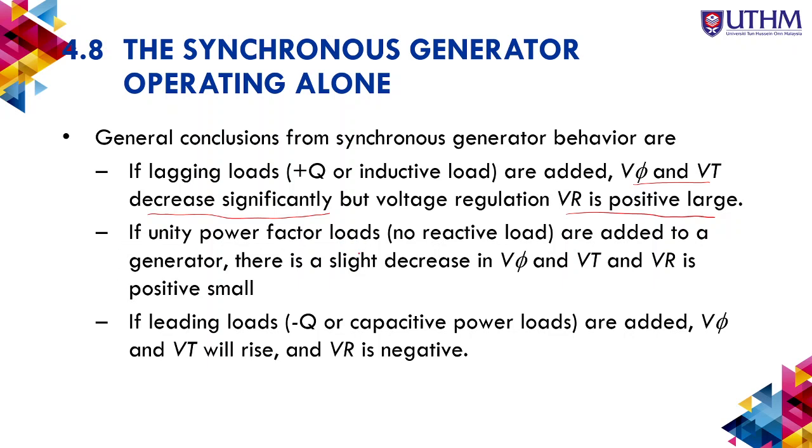If unity power factor is loaded, V phase decreases slightly, and the voltage regulation is positive but small. If leading loads are added, V phase and VT will increase, so the voltage regulation will be a negative value.